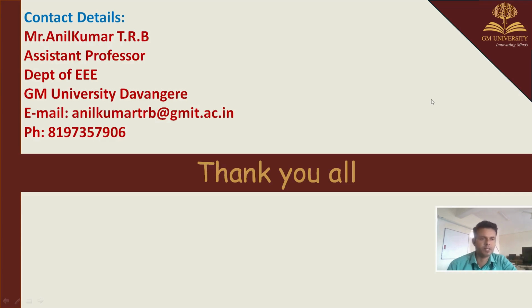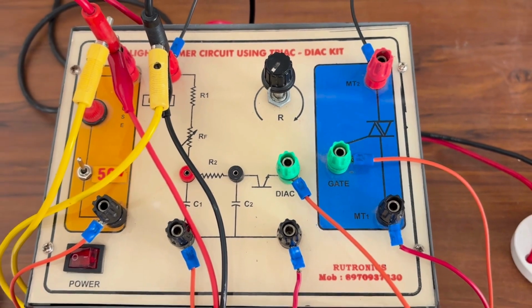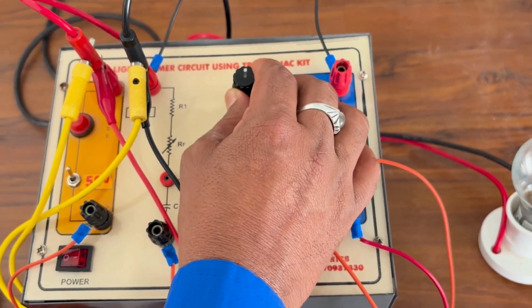So let us see how it works in the real-time experiment. Let us conduct the experiment and see what waveforms we can see in the CRO. I am Anil Kumar TRB, Assistant Professor, Department of Electrical and Electronics Engineering. Today we are going to learn the experiment on AC voltage controller using TRIAC and DIAC combinations. We have to make the connections as per the given circuit diagram. After making the connections, we need to keep the potentiometer at maximum, then vary the potentiometer from maximum to minimum positions.